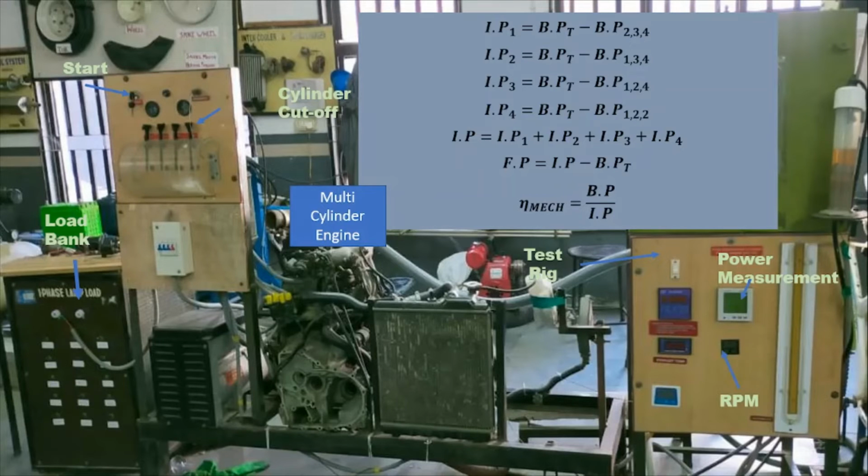Before starting the experiment, first check the fuel supply, lubrication oil, and availability of cooling water. First set the dynamometer to zero load, running the engine till it attains the working temperature and is steady. Adjust the dynamometer load to obtain the desired engine speed. Record this engine speed and dynamometer reading for the calculation of the brake power.